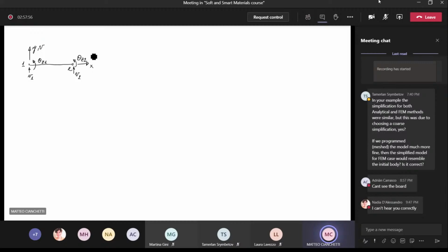In this analysis, we are considering bending deformations only and the displacement restricted to the xy plane, so that we can also apply the very simple and well-known Euler-Bernoulli theory that can simplify at least this exercise. All the approximations that we are doing analytically in order to apply Euler-Bernoulli are also applied to the solution that we are going to find with the finite element method.